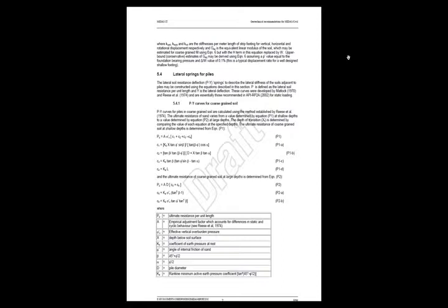Okay, there is a Benjamin. Hi, so Benjamin has replied to one of the queries here, and it says that the code does not apply live loading due to the ability of the suspension not to impact the bridge movements. So Christian, I think he has replied to your query. But yes, when you talk about buildings, I was talking in a more general manner. If you have live loads in a building, then you take into account a certain percentage of the live load to consider the mass. And if you are designing jetties and all, then it has to be considered. But I guess in live load, the suspension will take care of it. But yes, if you want to apply it, you can just add some of it to the self-weight of the structure and convert it into mass and perform analysis.